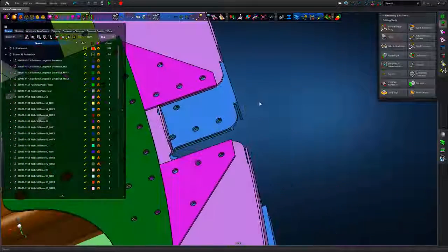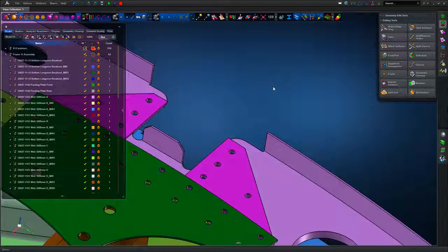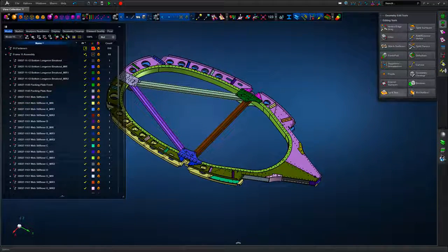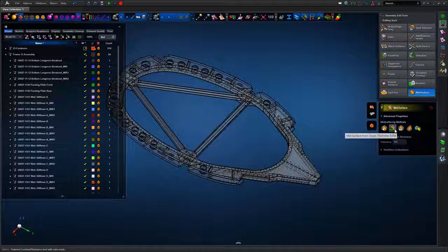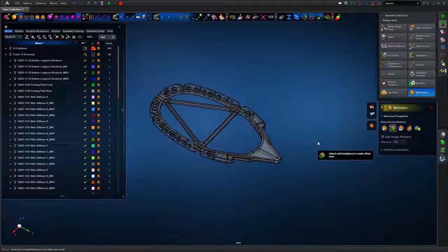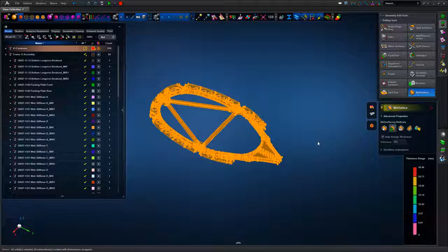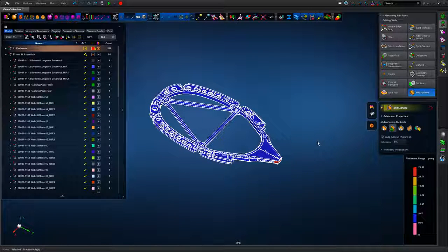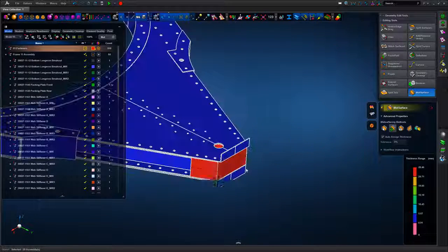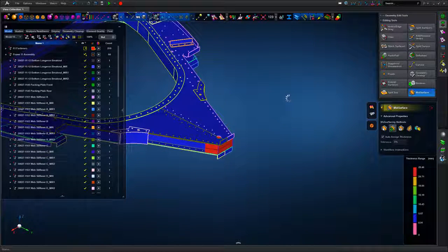So zooming in, we can see for a couple of those regions that the fillets have disappeared, and this again makes it a more simple operation in terms of our mid-surfacing, which we're about to perform. So we're going to use the mid-surface or single thickness solid with the auto assign thickness checkbox turned on. Perform the mid-surfacing operation. So Apex is creating the mid-surface and also the subsequent shell thickness property based on the original solid definition. So a very nice way of working quickly with the model. And we can see a fringe plot of the resultant thicknesses.